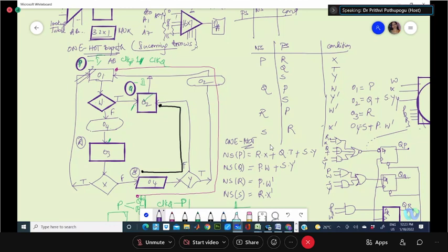The only thing is you will be adding flip-flops. So the complexity of the design goes up in one hot if the number of states is more, because direct flip-flops mean your cost of the design will be a little bit more compared to the mux method. But the flexibility is that you can add more states into your ASM conveniently.